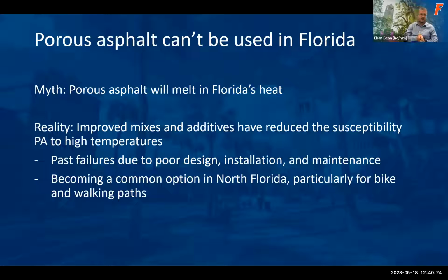Another myth is that porous asphalt can't be used in Florida, the idea that porous asphalt will melt in Florida's heat. That's not necessarily the case. We've seen some big changes in the mixes with porous asphalt over the years. They have really improved, particularly with some of the additives that help them to retain their strength in difficult high temperature environments. So the past failures oftentimes are due to poor design, installation, and maintenance.